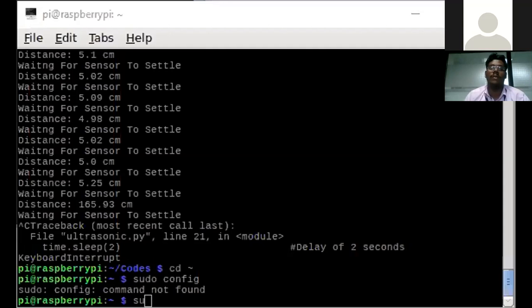After configuration, you need to do the basic installation. We need to install Python packages from pip and dev, and also we need to install GPIO packages. These are the basic key packages. So sudo apt-get install python-pip is one of the packages. It installs the latest version.